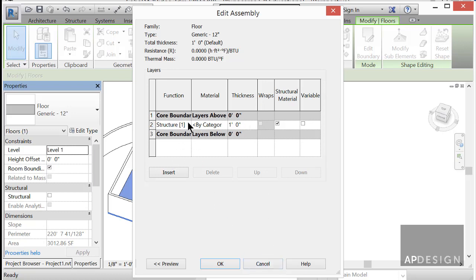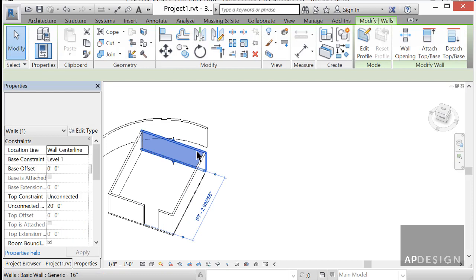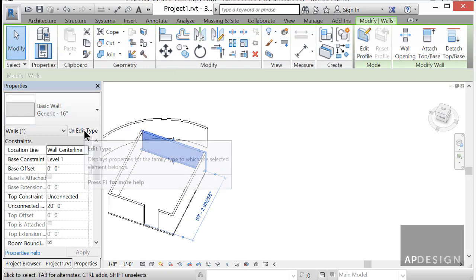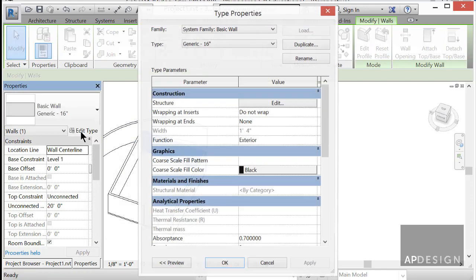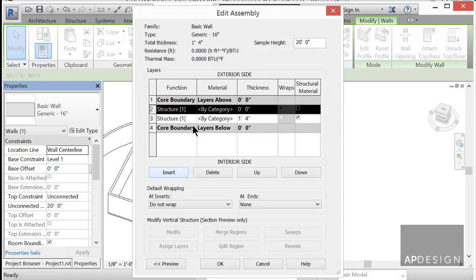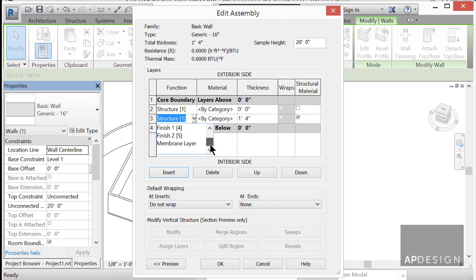Realize that there's also a bunch of information you can start to build, let's say in your wall type. So after you get through the basic schematics of a design, you might want to start to really think about the construction of each of these walls. So what you can do is go into that structure and start to build in multiple layers. And in each layer there's generic, whether it's finish, or a substrate inside, substrate being like plywood or rigid insulation, stuff like that. I guess the rigid insulation would actually be in this thermal barrier. And you start to layer up what each one does.